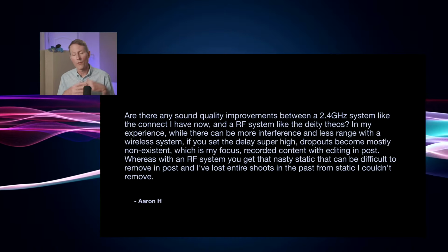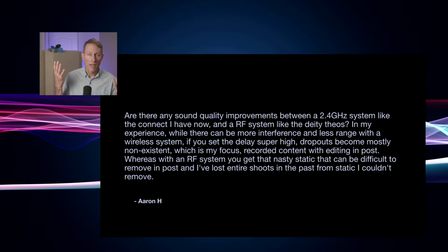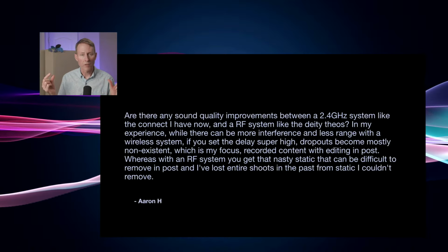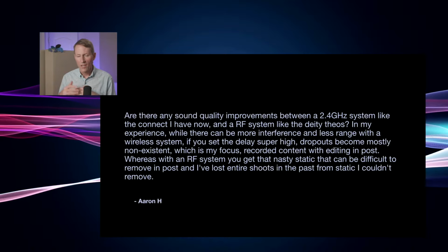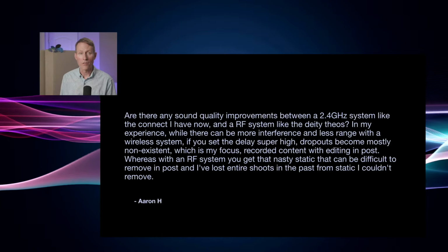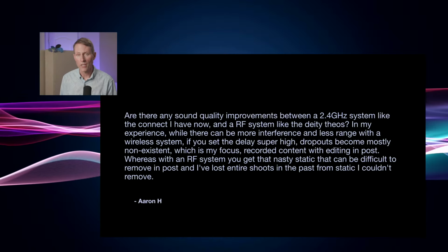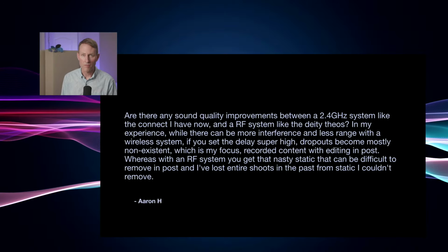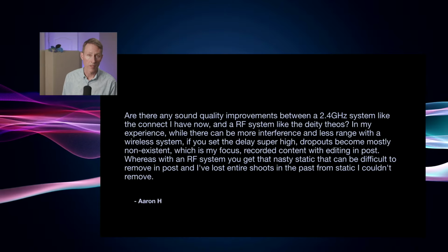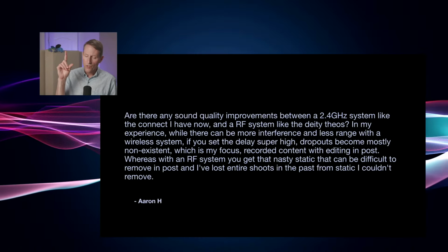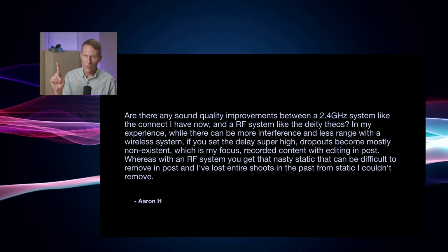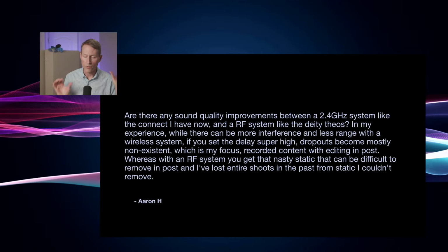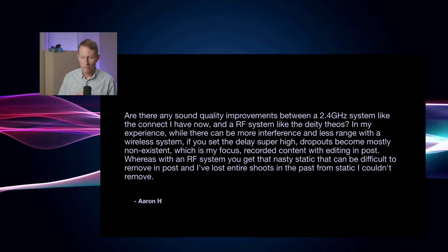If you're doing field recordings and you're very particular about having pristine higher frequency response and no artifacting, then yeah, it's going to be a problem. If you're just recording dialogue and you're going to roll off above 15 kilohertz anyways, then it probably doesn't matter. So short answer to your question, no, you're not necessarily going to get better audio quality just going from 2.4 gigahertz to UHF.